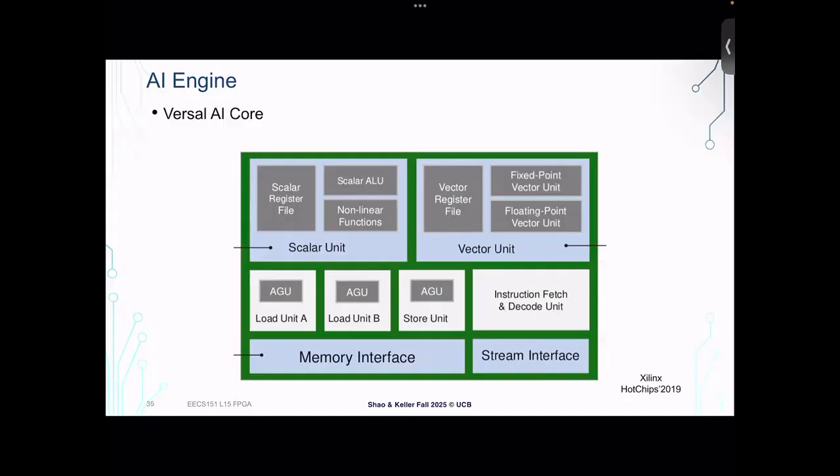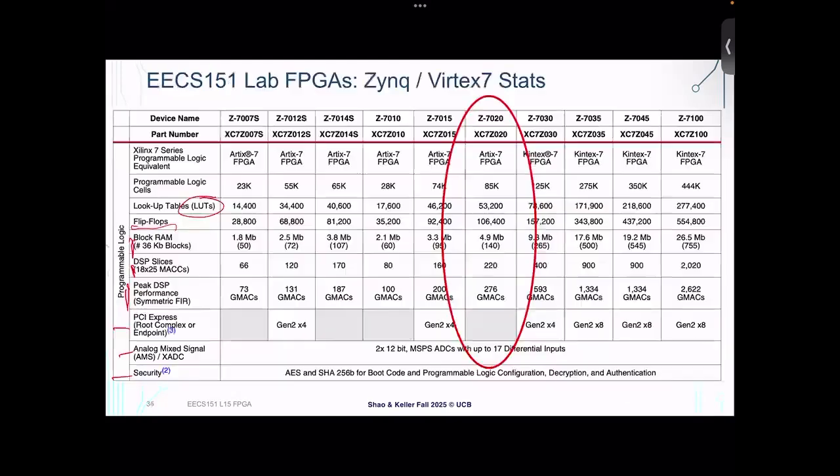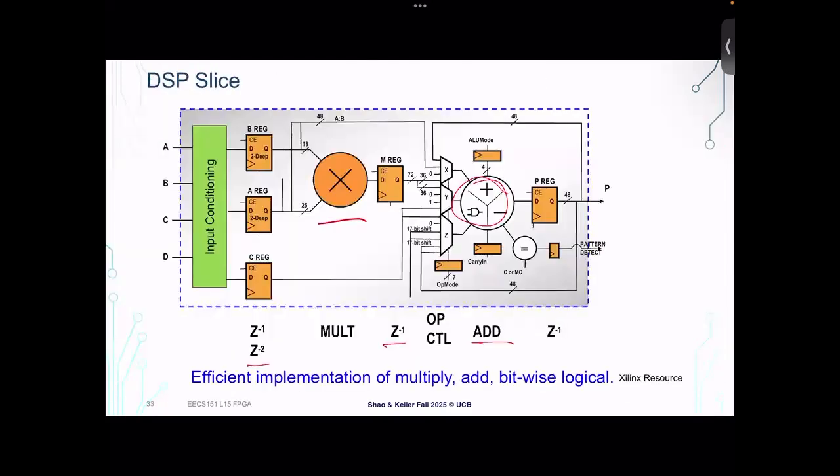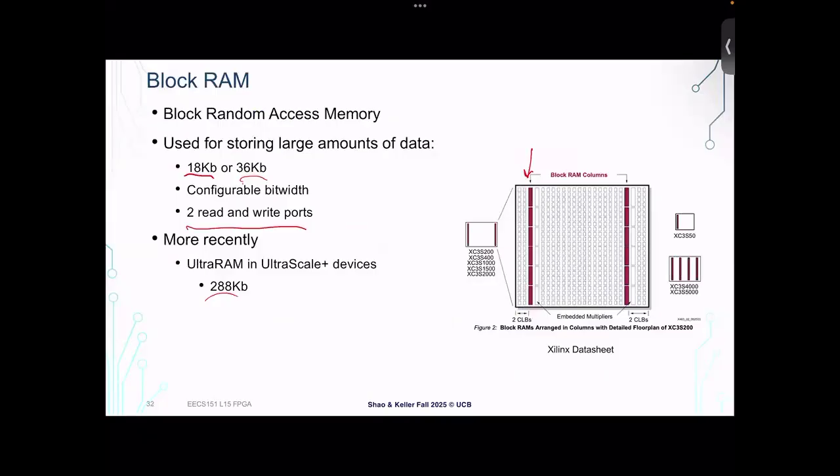Yeah, so block RAM is, under the hood, made of the same fundamental building block as SRAM. But block RAM is the name of the SRAMs that are instantiated on the FPGAs. It's called block RAM because it comes in these predefined sizes of blocks.